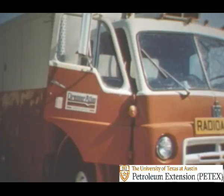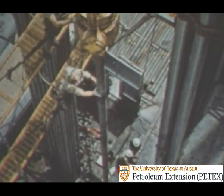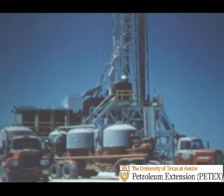Since the oil mud is non-conductive to electric current at voltages normally used for electric logging, usually a radioactive or sonic log is run. After the log is interpreted, a liner is set from the 9 5/8" casing through the pay section. With the liner run into the hole, a cementing company arrives on the scene.